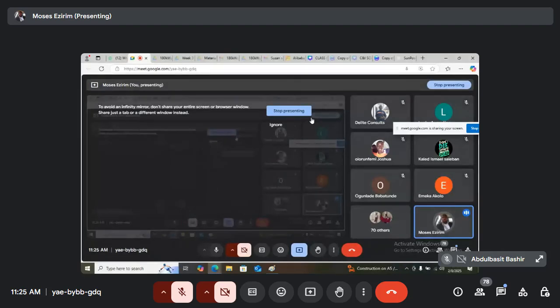For example, let me assume that somewhere in Kano, the solar irradiance, I mean the sun in Kano, is more than in Lagos. But where I want to do my installation is dusty. I can decide to use half-cut cell because it's dusty. It can get to a point that some dust can begin to cast shadow on my module. But if it casts shadow on my module, at the end of everything, I can still realize my money easily. You understand? Because of the solar irradiance, because of the sun that is there. But somewhere in Lagos, the sun is not that much compared to Kano. So when I do my plus and minus regarding the energy from the sun, I can decide to go with full cell. That's a full cell monocrystalline.